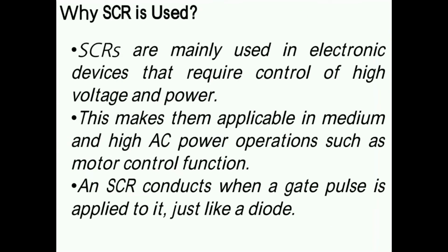Now why is SCR used? SCRs are mainly used in electronic devices that require control of high voltage and high power. Whenever we want to control high voltage or high current, at that time the SCR is more suitable. This makes them applicable in medium and high power AC operation, such as motor control. If you want to control the speed of a motor, SCR is used for high power applications, and SCR conducts when a gate pulse is applied.